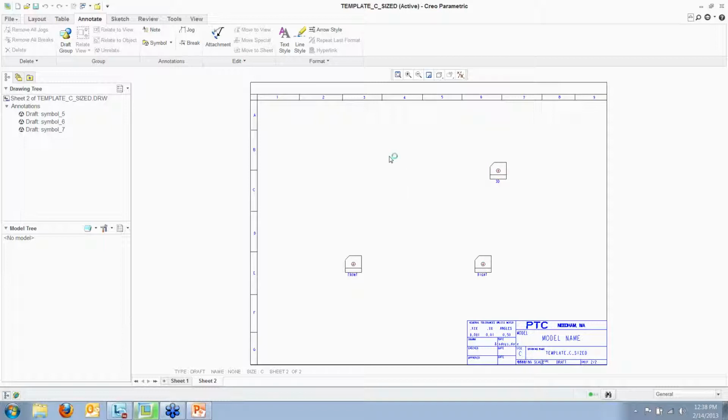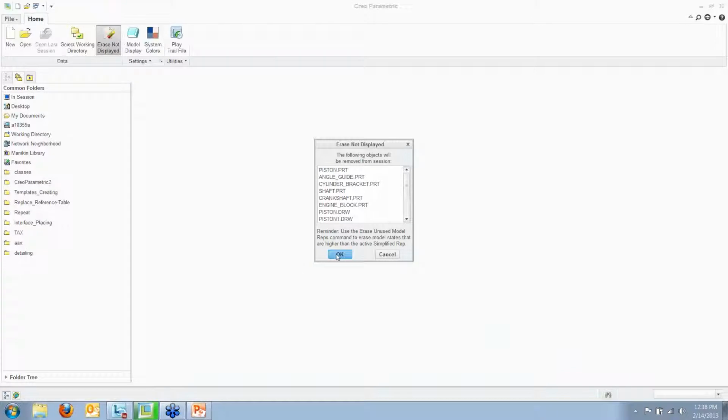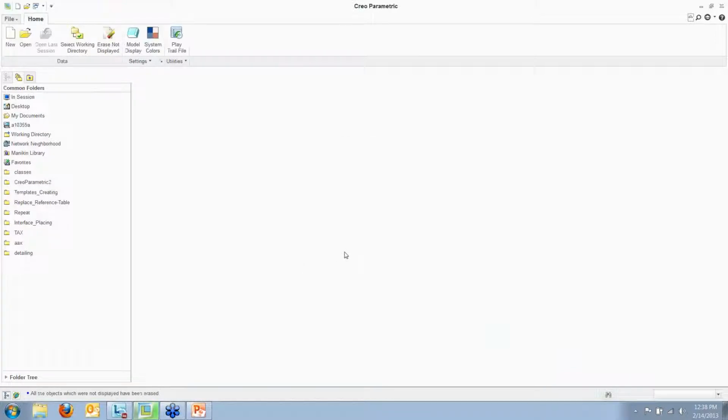So you'll want to do that all at the template level. You don't want to do that after the fact. If you notice yourself doing the same thing to every single drawing you create, put that information in the template, which then will allow you to quickly and easily create your drawings. Okay, so let me take another step back. Hopefully you guys understand the value of using templates. Hopefully you didn't get too discouraged by my ranting and raving there.